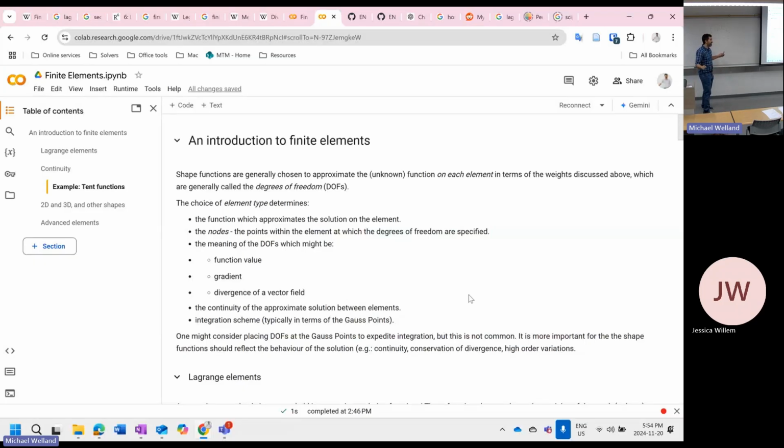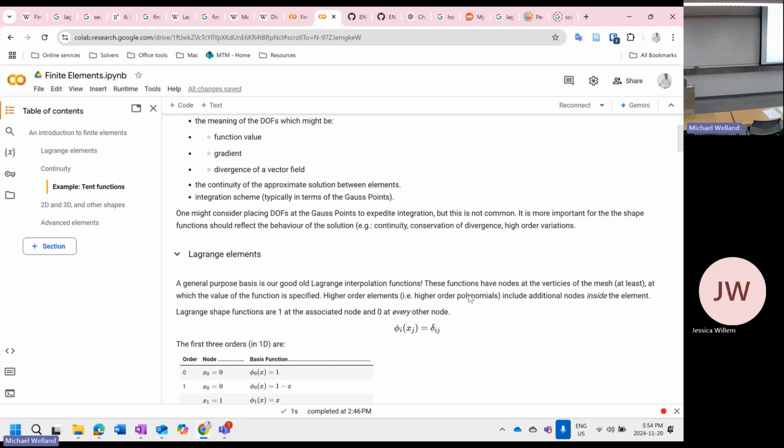An alternative is something called, for example, the Hermite element, where instead of the value of the function at those nodes, what you want to calculate is the slope. So this degree of freedom is the slope there, that degree of freedom is the slope there. And what that means is that the slope is the continuous parameter between your model, which means different things for your other physics. Come back to that one in a second.